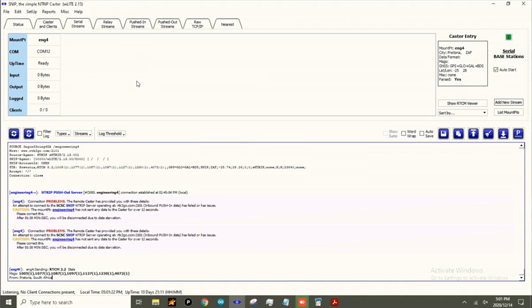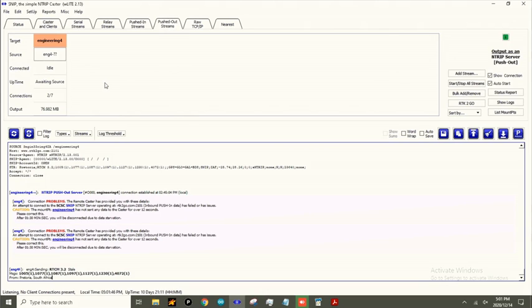So back to SNIP, this is where we're going to take our serial stream data. So this is the third tab. You'll see COM port 12 over there once again. We're going to take this data and we're going to push it to that particular mount point on RTK2Go. So that is where the push out stream tab comes in. And you will see that we already have that configured for this example.